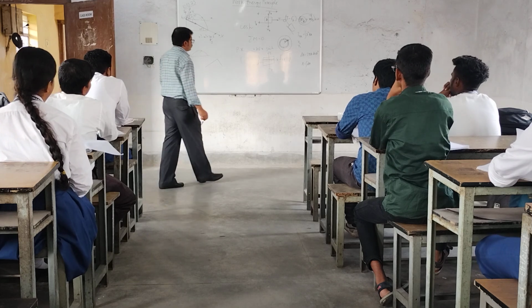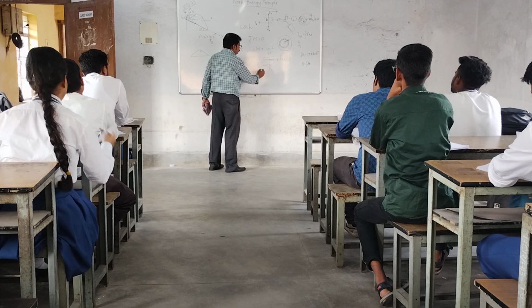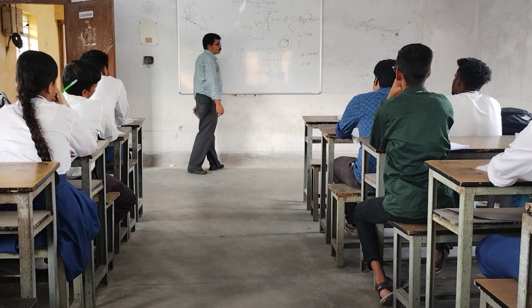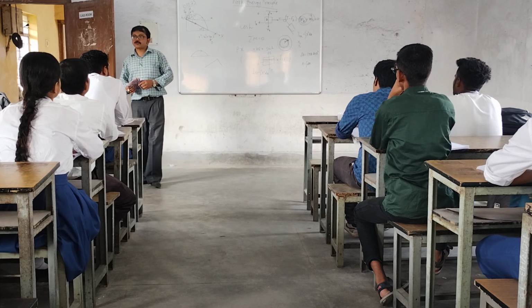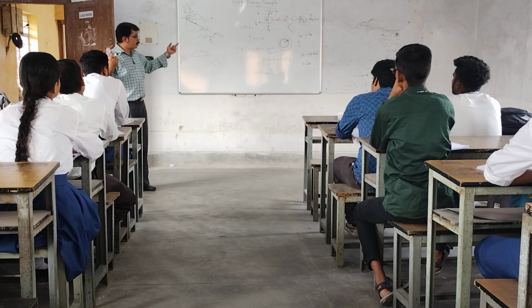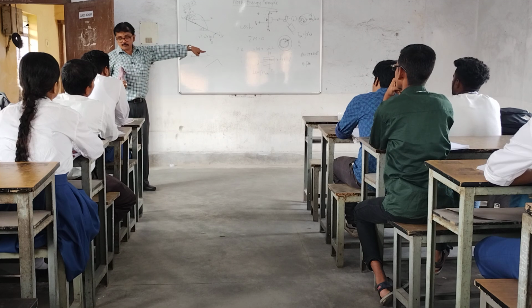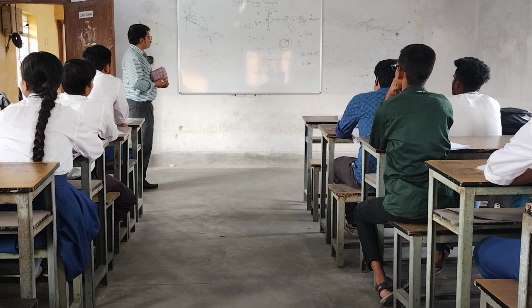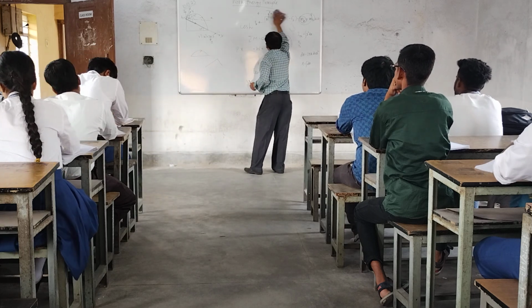But actually I_ZZ, when you are calculating, I_ZZ is equal to integration r square dA. So here r square is coming. R square is not coming in calculation of area. R square is coming when you are finding out the moment of inertia, not mass moment of inertia. Here r square, that's why r cube is coming. So these kind of mistakes should not be repeated unless and until you practice.